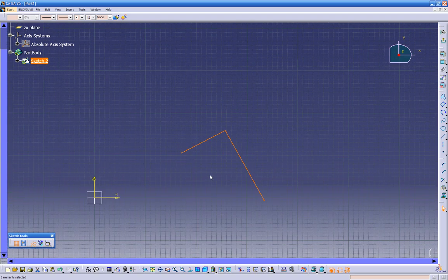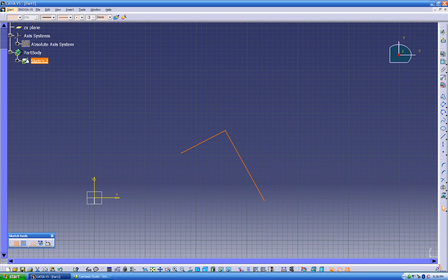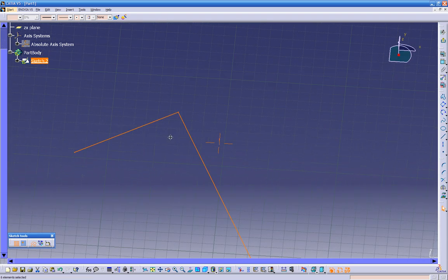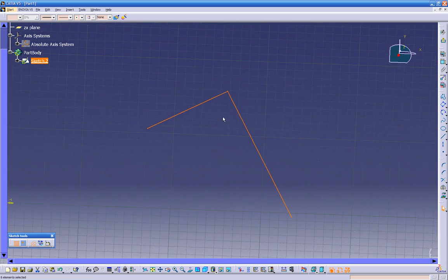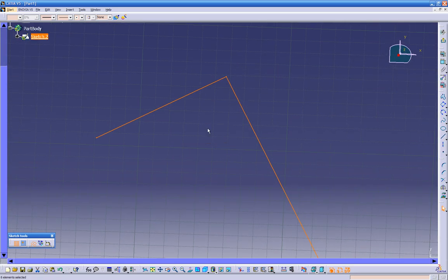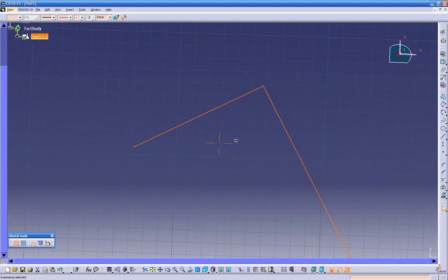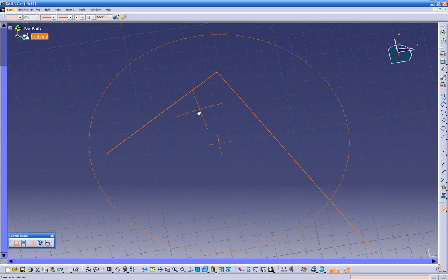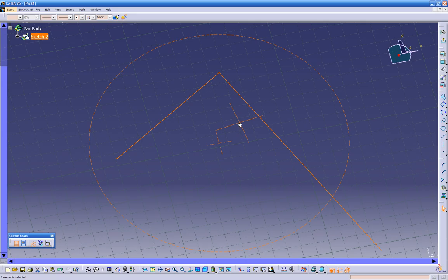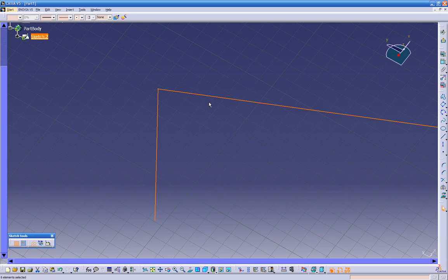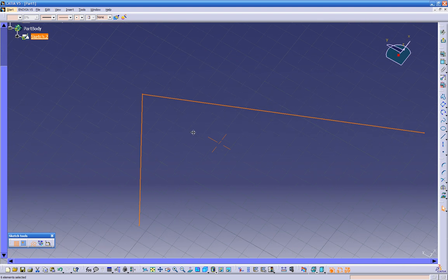It was going to be kind of hard in the beginning to get used to the mouse. It was hard for me when I first started to rotate, zoom, and pan. So once again, probably by now you already got used to it, but the middle button, just click it once, we get the panning. Right click and hold it. Now I have both of them clicked. I have the middle clicked and the right button clicked. Now I'm able to rotate. And if I want to zoom in and out, middle button, hold down, ready for the panning.